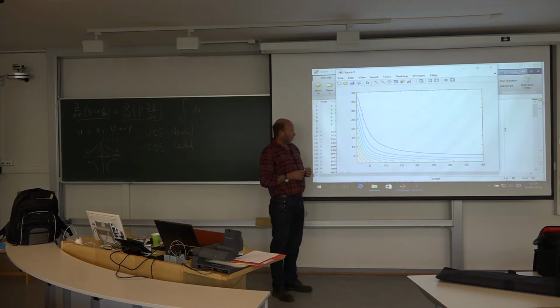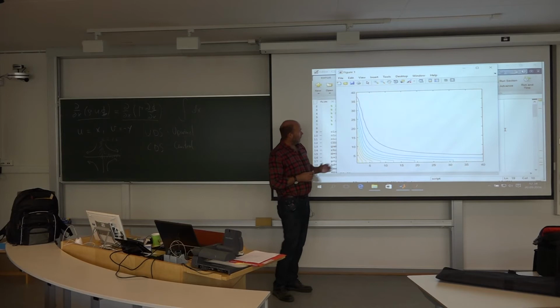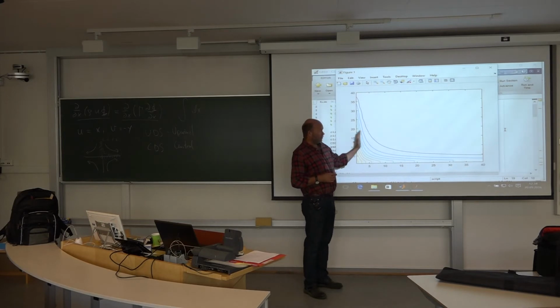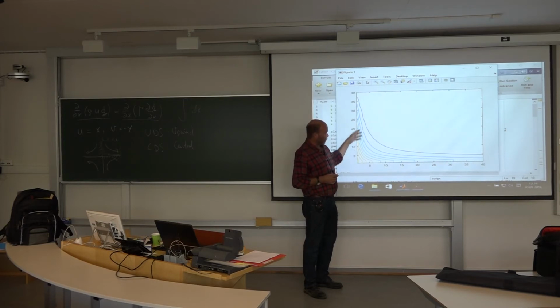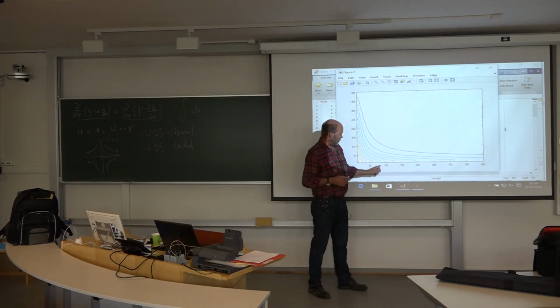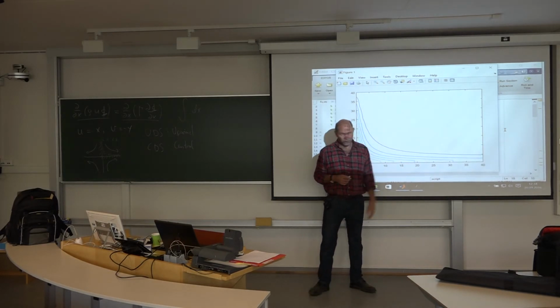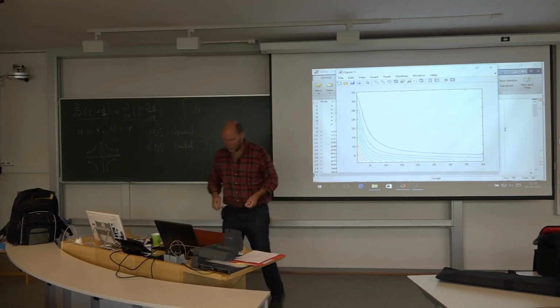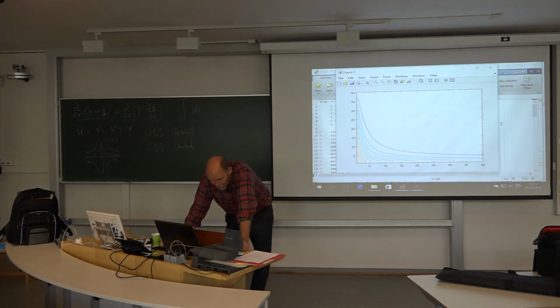So here you have the solution for the first order upwind scheme. And as I said, you have some diffusion. Some of this unknown phi is diffused into our domain and then transported, and then you have the outlet. This here is just the last cell, so that's just cosmetics. So yes, it actually finds the solution.